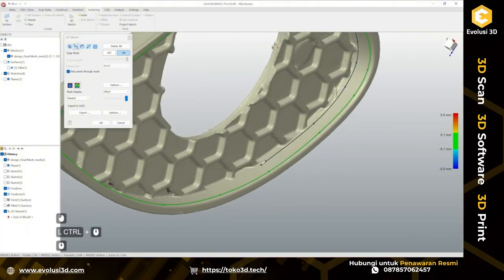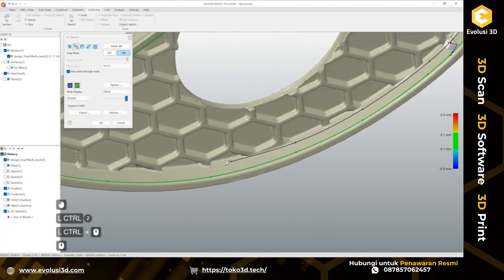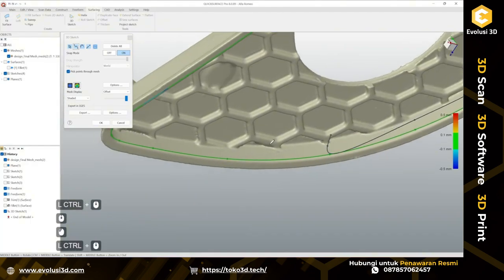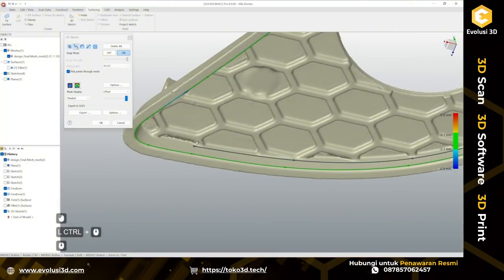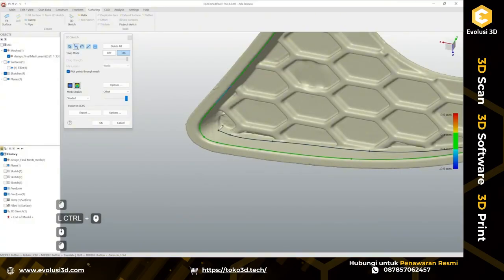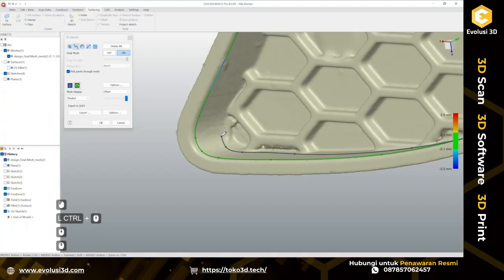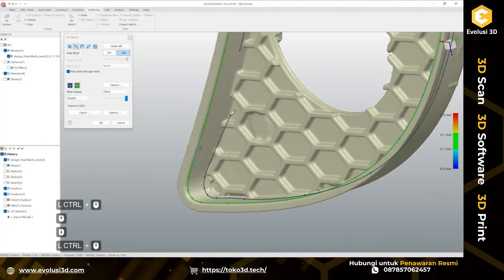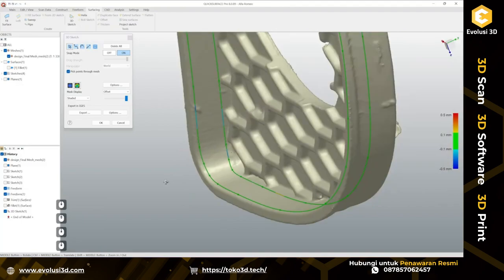Simply, if we don't have the same amount of vertices, it might start to twist somewhere and create undesired results. But in these cases we can also create additional guide curves to compensate for this and get rid of unwanted results. Okay, so something like this.